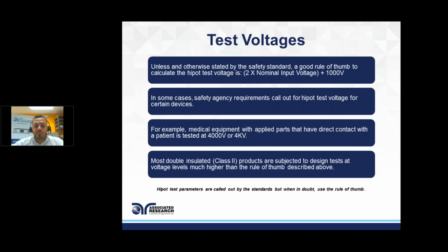How do we set our test voltage? Now, we get a lot of calls from customers with this question. I've just bought my instrument, I've turned it on. The default is at 1.24K. What is it supposed to be at? What's my high limit supposed to be at? Well, these are questions to pose to the standard you're testing to, and these are also questions to pose to the lab you're certifying with.